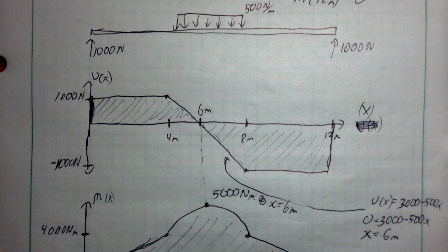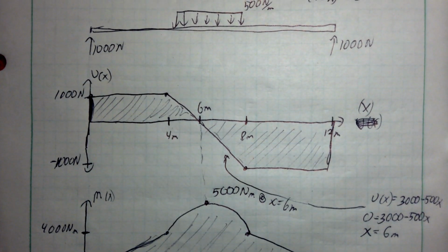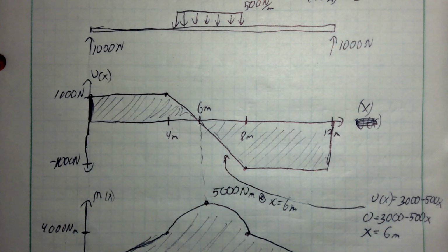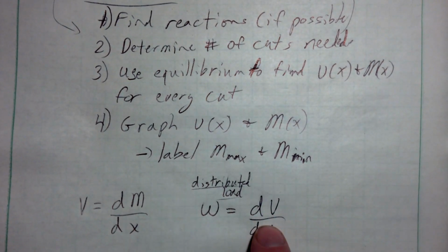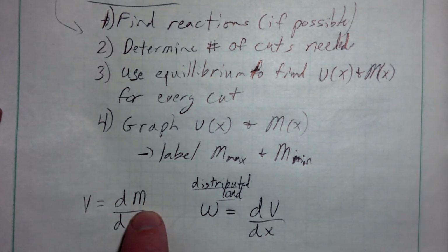Now, real quickly here, I'm going to get most of that on the page. Notice you can apply calculus principles and solve this problem. As we've already said, the shear and the distributed load are all related through calculus. We said the distributed load is the derivative of the shear. We said the shear is the derivative of the moment.